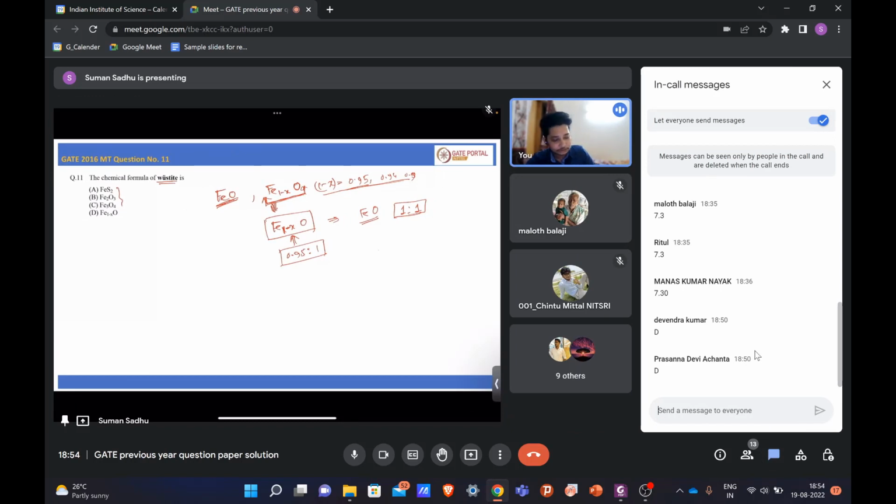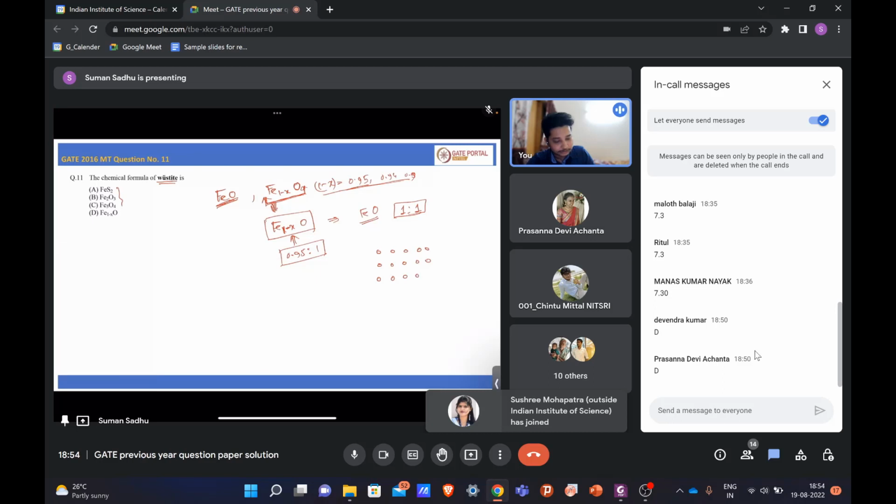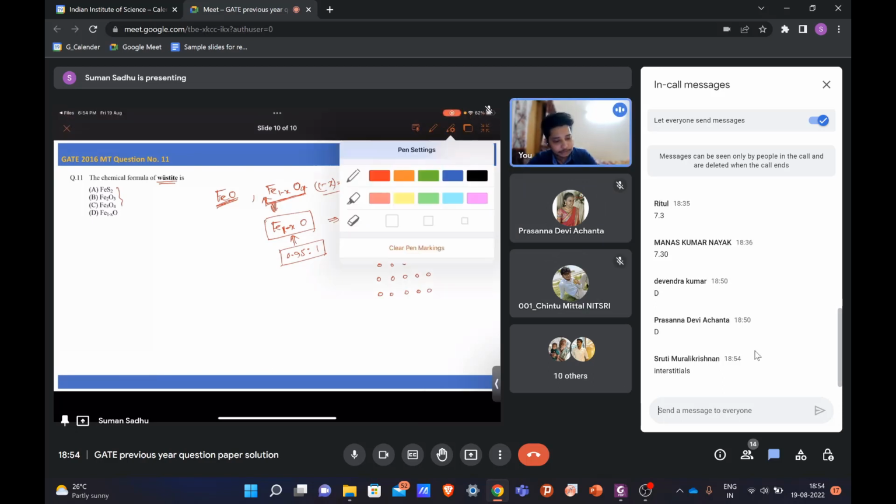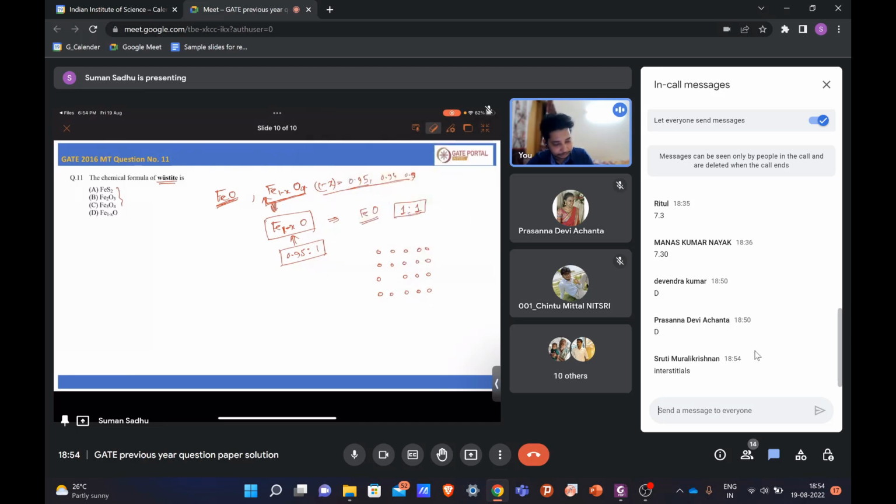In a crystal also there is a regular distribution of atoms, right? Yes, vacancy is one type. So in case of metal, you will find that maybe some atom is missing from here. Let's say this is a vacancy. A vacancy is one kind of point defect. Similarly, it may be that this atom moves to these positions, so it is like an interstitial defect.